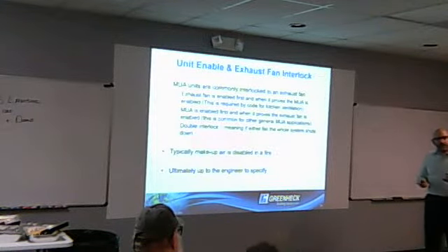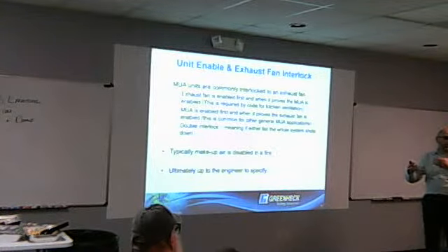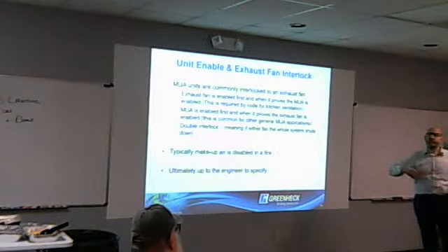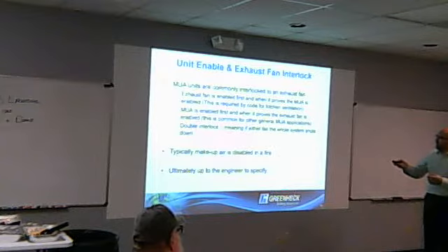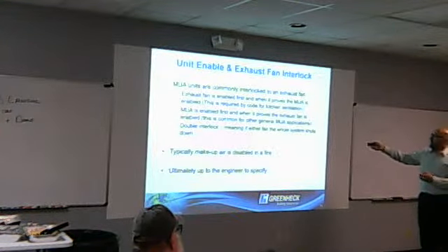Okay, so you bring your makeup air because you have a fast system of exhaust. So normally you're interlocking areas. The exhaust fans come on and suck air out of the building, so let's turn on the makeup air. Those are interlocked, and makeup air is enabled first when it proves the exhaust fan is enabled. So it just kind of depends on the application.